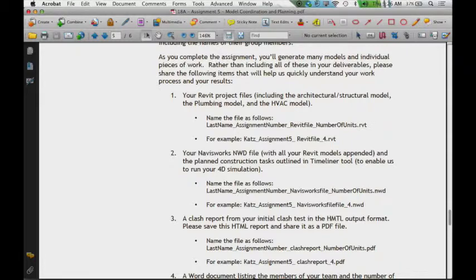Now, 9 times out of 10, it'll be something about the ductwork and the beams just trying to occupy the same space. At which point we try to find those clashes. If we find some clashes, we say, hey, we've got to do something about this. Either we shrink the beams or move the ducts so that they're not intersecting with the beams. And then ultimately just resolve those. Sort of make sense? Okay, we'll leave it at that for now.